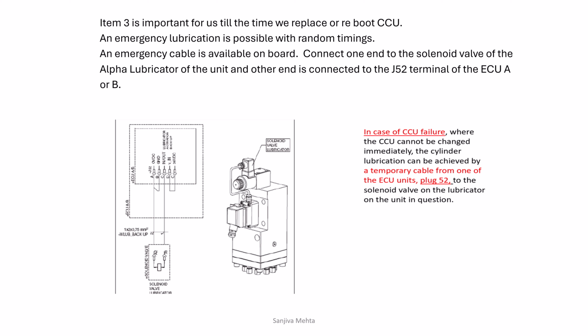Replacement can be done even when the engine is running, because all the functions have already stopped and you have already started supplying cylinder oil. So replace, remove this, put another one, and then start again. When it starts working, increase RPM slowly once again. Remove this emergency cable,